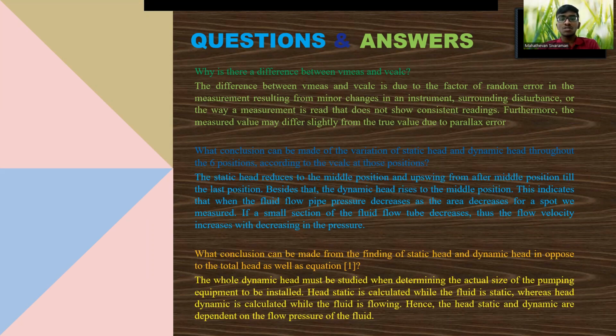The final question, what conclusion can be made from the finding of static head and dynamic head as opposed to the total head as well as equation 1? The answer is the whole dynamic head must be studied when determining the actual size of the pumping equipment to be installed. Head static is calculated while the fluid is static, whereas head dynamic is calculated while the fluid is flowing. Hence, the static and dynamic head are dependent on the flow pressure of the fluid.